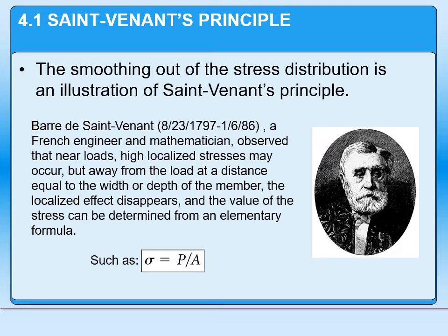He specifically noticed that when the distance is equal to the width or depth of the member, this localized effect disappears. And we can use the simple formula for stress that it's equal to just the load divided by the area. And this is referred to as Saint-Venant's principle.